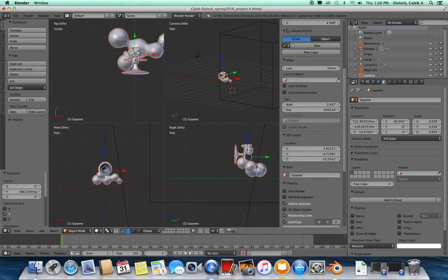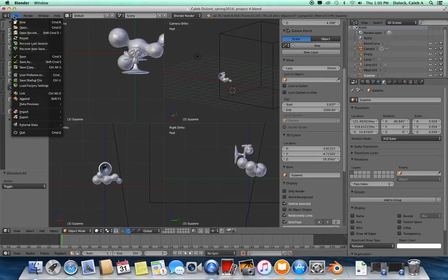And right now with all my objects selected, the location of this axis is also the same location that Augment will use to rotate my object based on, or to position it from. So I'm going to position the center of this axis kind of roughly over the intersection of this green and red line. All right. Now I've got it set, it's above the line, it's aimed in the right direction. We're good to export. So we're going to go up to File.